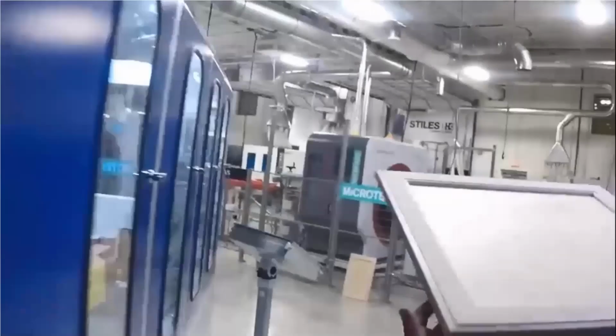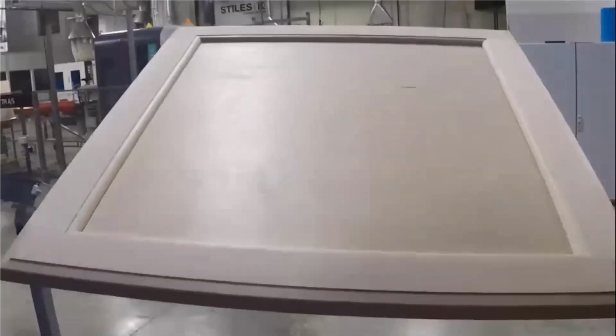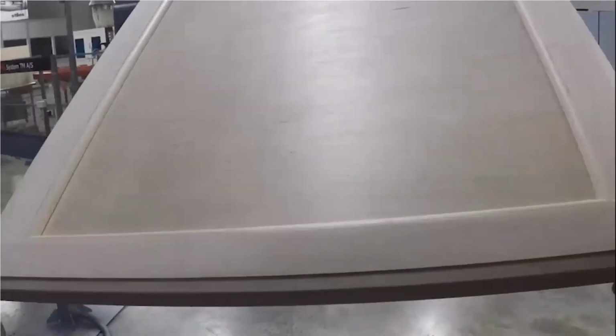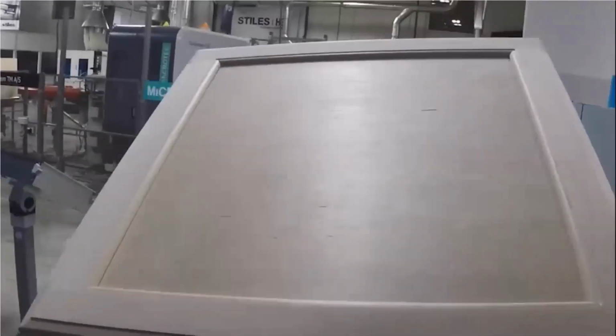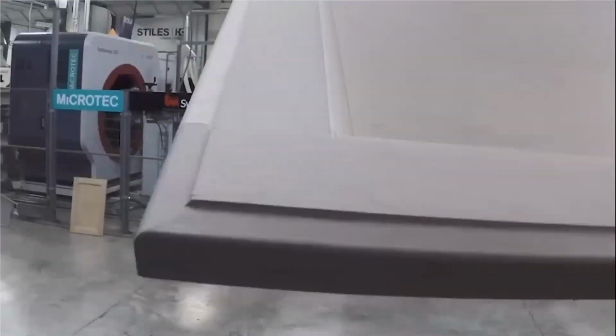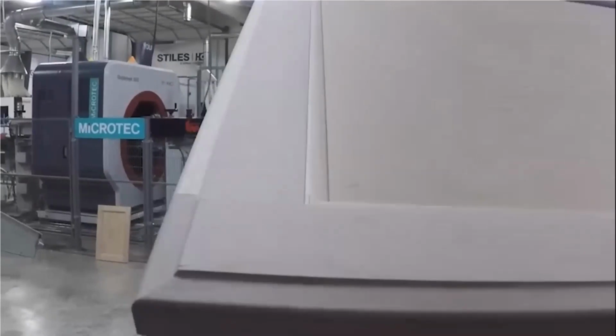The stain will bond. All the cross grain scratches have been removed at this point. So this cabinet door can be taken straight into your finish line and should be finished within 24 hours. And again, you can save those different recipes for more or less aggressive edge break.